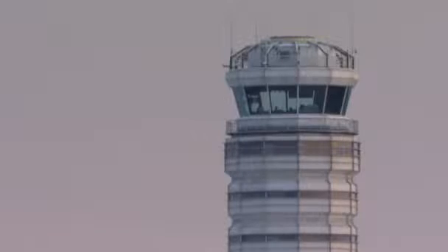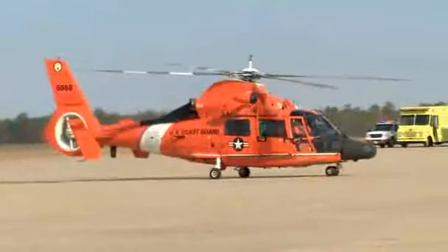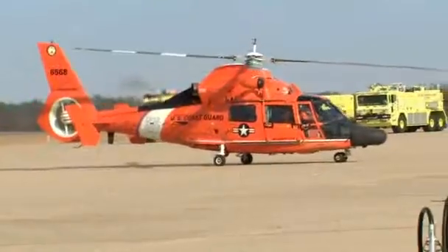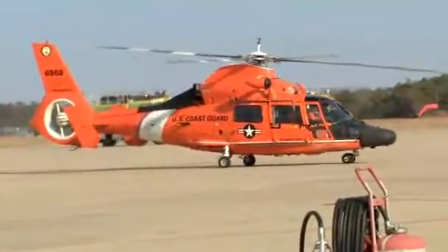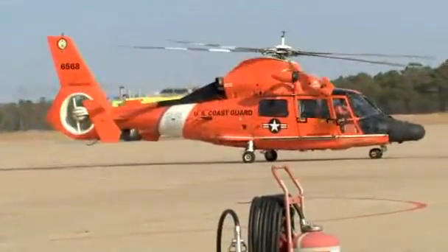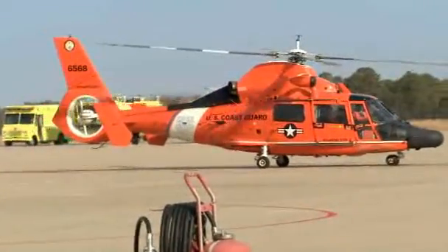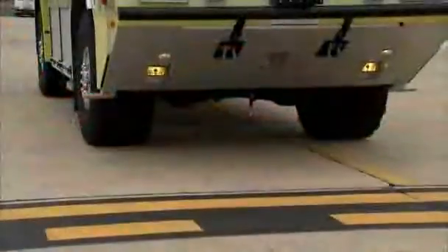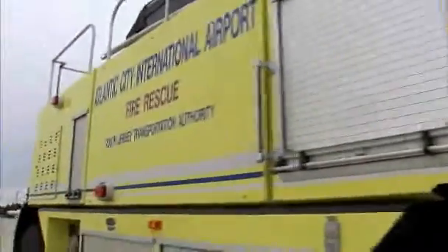Report clear. Air traffic control may issue a hold short command to ARFF vehicles moving in airport areas. ARFF vehicles may also receive instructions permitting them to move only after allowing an aircraft to move in front of them. Acknowledge clearance by repeating the instructions and your call sign. Crossing runway 31, ARFF-2, over.